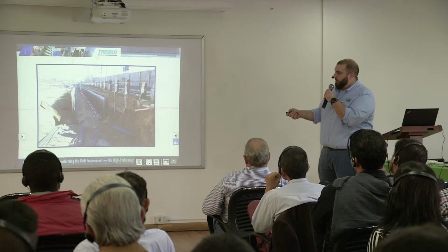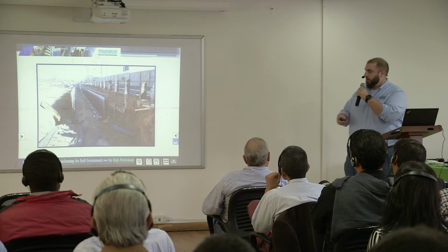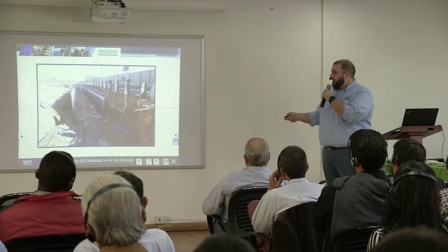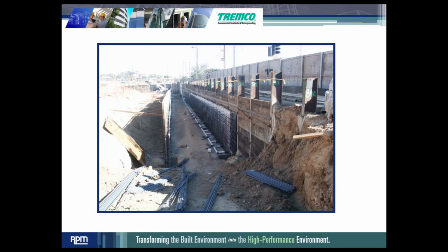Here's what I was talking about where I said you could have the drainage in the hole. It would be under your foundation slab in this situation. And this would be sloped downhill to leave the pit to go to a city drain or city sewer or something of that nature.